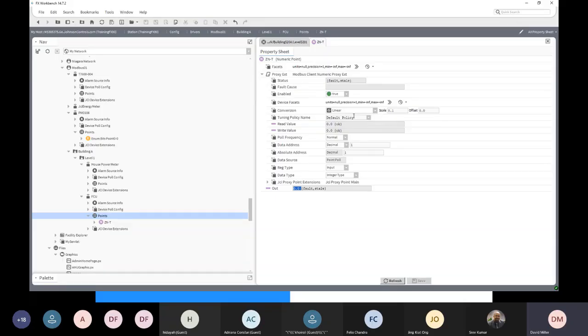And that's a very common conversion in Modbus. A lot of things, particularly temperatures, are sent through as an integer, and you divide it by 10. So that's our zone temperature done. So we're on site, we've connected to the zone temperature, and we're seeing a value that makes sense.